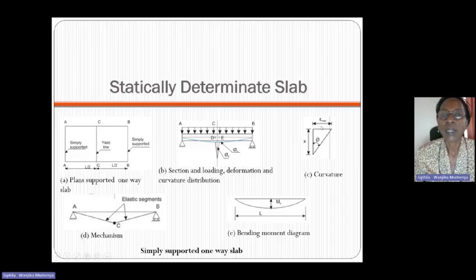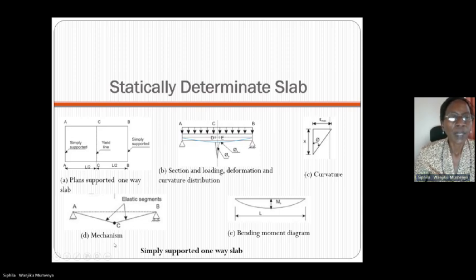That is just an enlarged curvature where you have the maximum strain. X is the distance to the neutral axis, and that's the angle phi. If you look at it from the strain diagram of a rectangular section, then if the load keeps on increasing, up to the yield line at point C, you have your plastic moment.